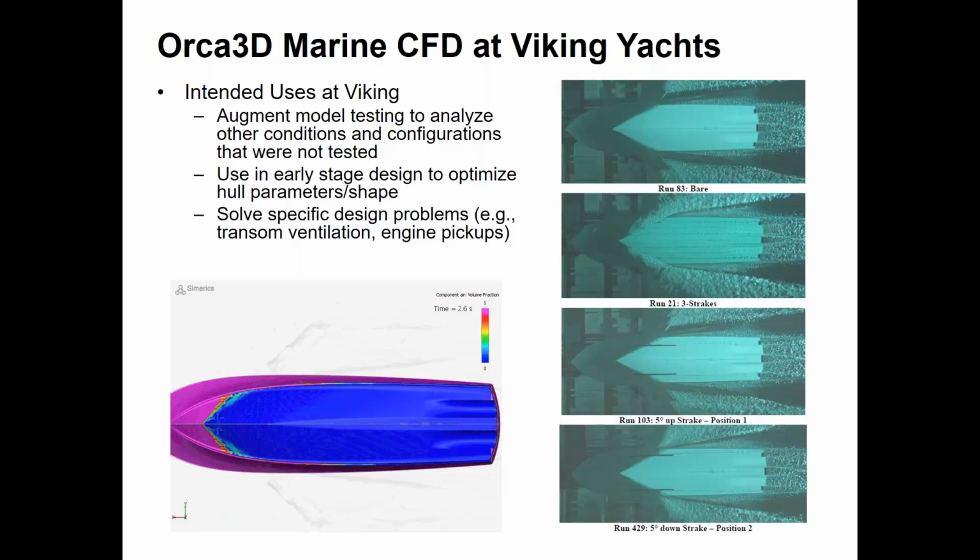And then early last year, we did a cockpit extension on a hull, and we had trouble initially with that hull getting up on plane because the cockpit extension was acting like a step, and we had not ventilated the extension.